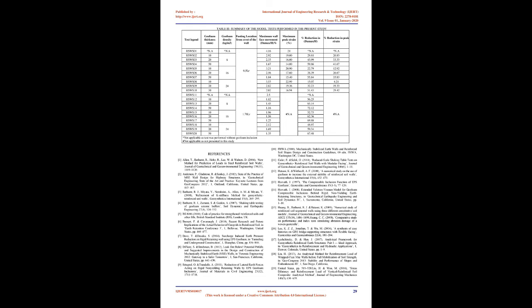Wall face movements were observed to be significantly higher at the top middle third of the height of the wall when footing was placed over the reinforced zone. This is mainly due to the fact that the tensile resistance in the reinforcements gets developed with settlement of footing. The topmost geogrid layer was observed to get held and pulled back towards the footing, which is mainly due to the fact that the anchorage length of the geogrid of top layers falls below the corners of footing and thus restricts the lateral movement of the crest of the wall.